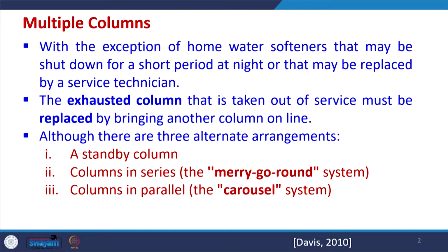During that period, the exhausted column which is out of service is regenerated, or if we have to replace the beads, we can replace the beads also. While this regeneration is being done on the exhausted column, the treatment is being done by the other 3 or 4 columns.